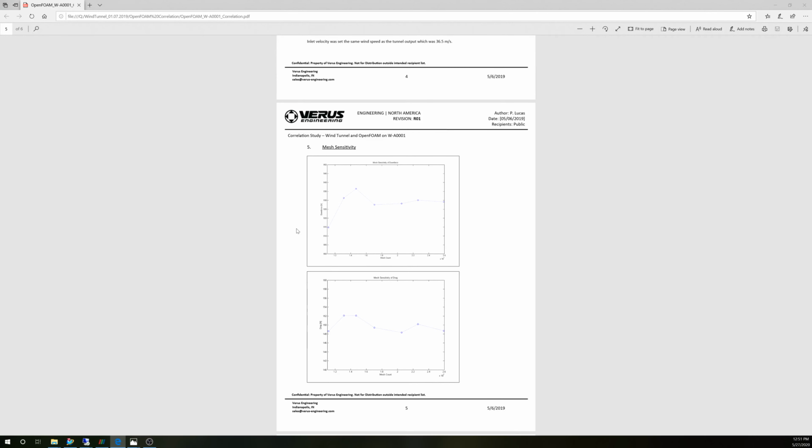Before that, all we had was trends off track data. We did use strain gauges on wing uprights to figure out forces, but you're still dealing with messy data on the track, so it's very difficult to correlate that back. So the wind tunnel made the most sense for us. There's a local wind tunnel here but it's scaled, and we obviously couldn't afford to build a scale model of a car and test that. It just doesn't make sense for what we do as a company. But the wing did make sense.